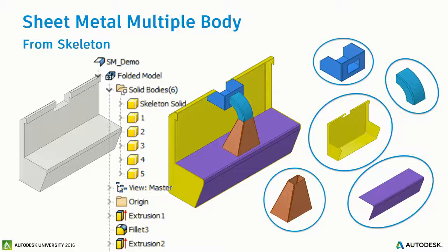In a lot of cases, like you said, they've created some sheet metal parts, and we've got to do both. We've got to do multi-part bodies and do our own parts. Actually, we can import single body or multi-body assemblies from third-party software. You can import the third-party data set into Inventor as externally or multi-body. And when they update during the design process, I bring in their model again.